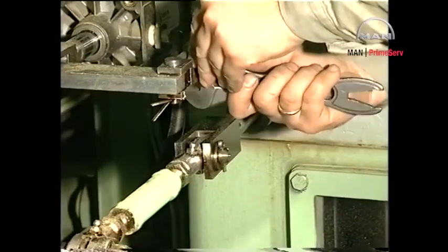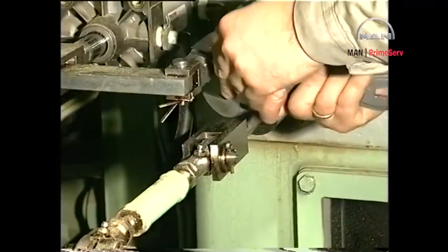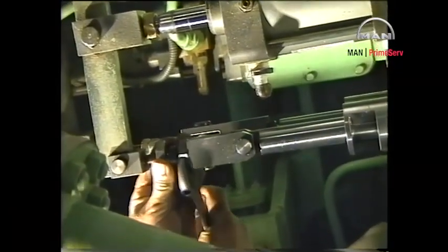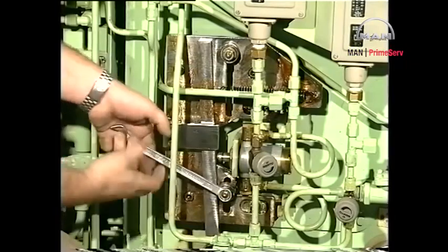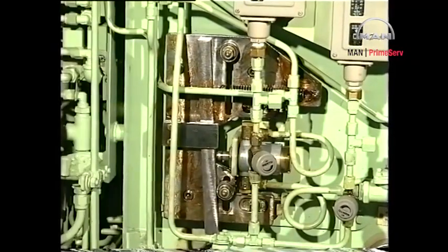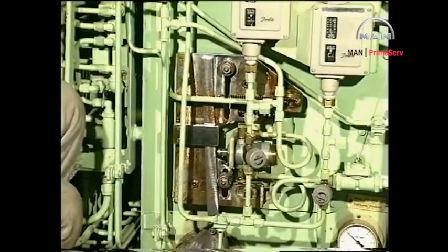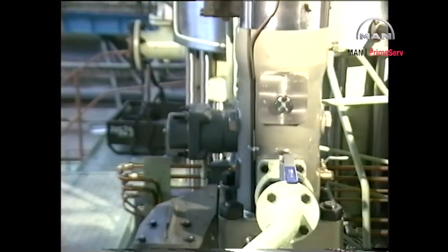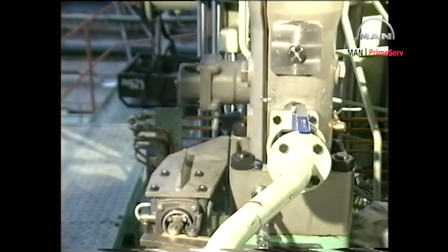Fine adjust the links so that the maximum combustion pressures corrected to ISO ambient conditions are uniform and have the required value. Load the engine until it corresponds to 100% MCR and fine adjust the lowermost pivoting point so that the maximum combustion pressures corrected to ISO ambient conditions are uniform and have the required values. Cams must be turned if the value calculated in step 1.4 of this film is exceeded.